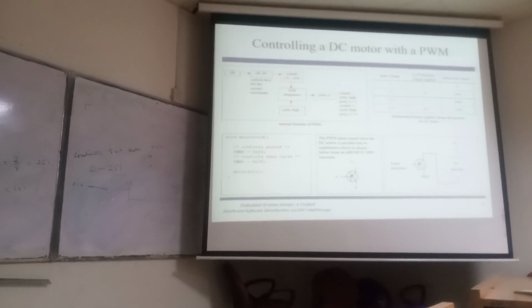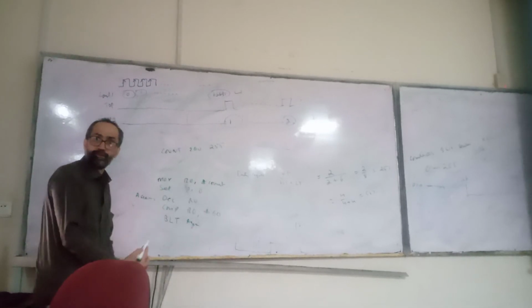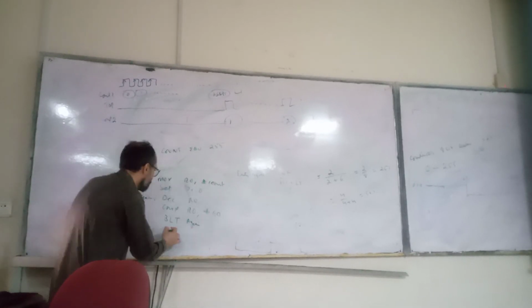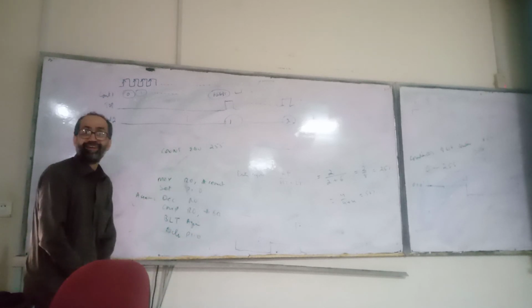Branch if equal. If it is less than 64, it should jump again. Again decrement. And when it comes out of the loop, then we should clear P1.0. We make a simple delay function, a delay function.